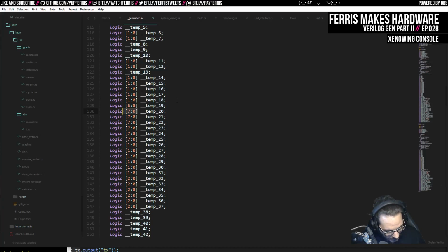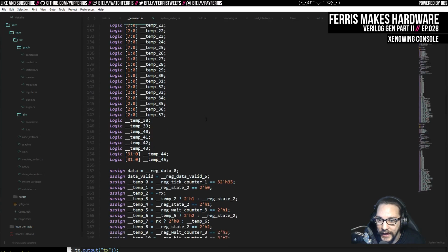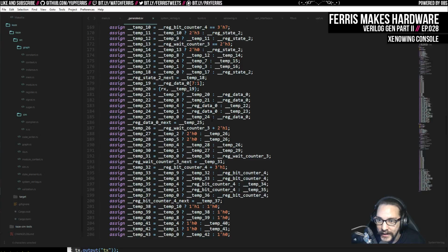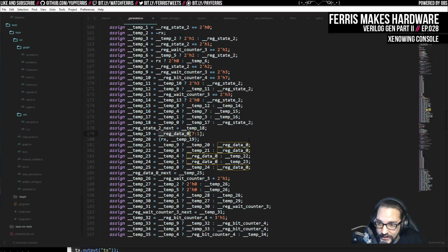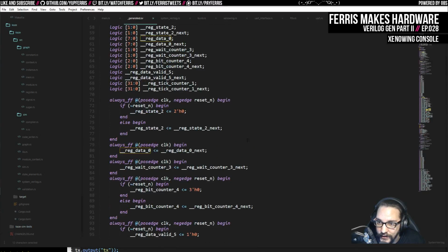And that's also why, I don't know if we actually looked around in Vivado on the stream, but I was never able to find the data register. What was happening is that after synthesis, things would be optimized by the Xilinx compiler.